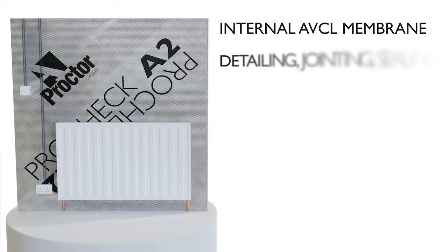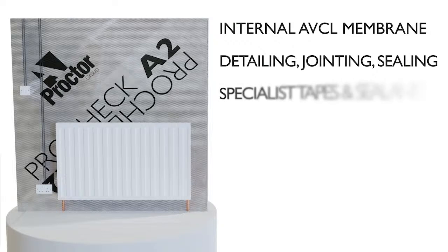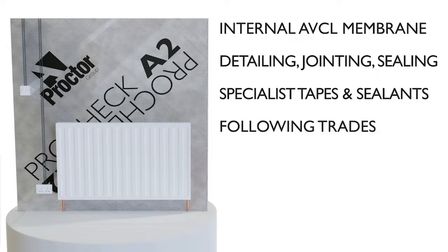If this approach is taken, the correct detailing, jointing, and sealing of the VCL become very important, and any gaps or damage will affect the air leakage. Penetrations for building services such as power and plumbing must also be fully sealed. Achieving the degree of sealing needed to achieve a low air leakage rate requires multiple specialist tapes and sealants, airtight sockets and switches, and above all, experienced and highly skilled contractors. Following trades during construction and in the future also need to be aware of the importance of this airtight layer and have the skills, experience, and materials to undertake their task without compromising it.